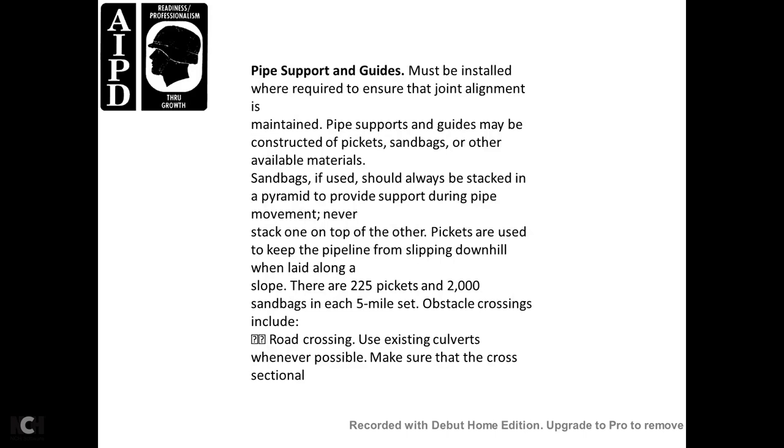Pipe support guides must be installed when required to ensure the joint alignment is maintained. The pipe supports and guidelines are constructed with pickets, sandbags, and other available materials. Sandbags used should also be stacked in a pyramid to provide support during pipe movement.